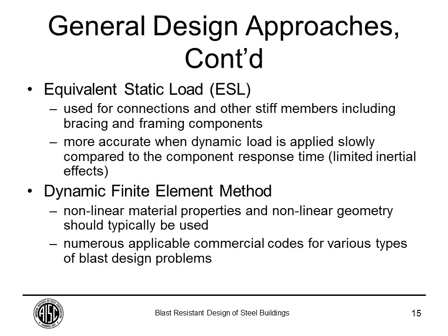Next, we have the equivalent static load. As the name says, it's a method in which we calculate an equivalent static load that is based on the ultimate flexural dynamic capacity of the member. In other words, we calculate the maximum reactions that those members can transfer before they fail. This method is generally used to calculate connections and components at the end of a load path.